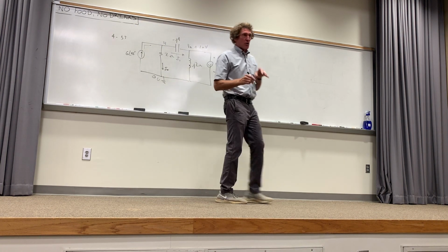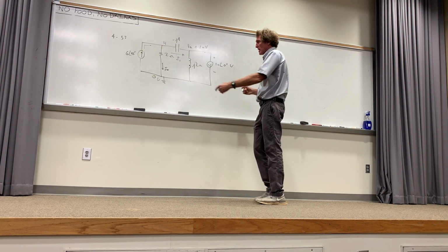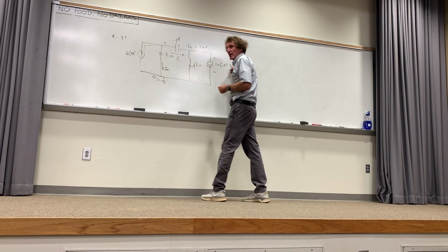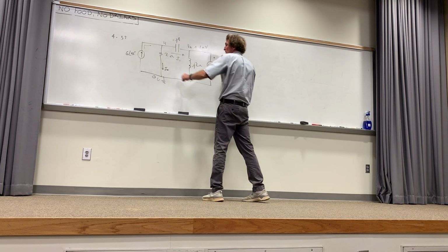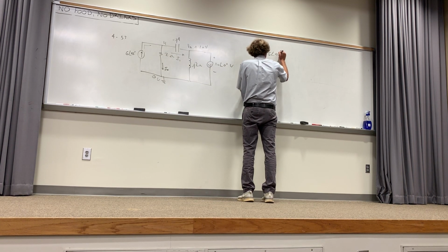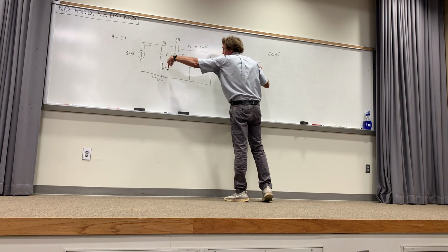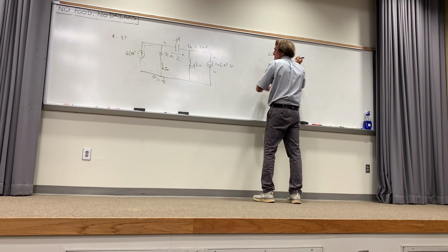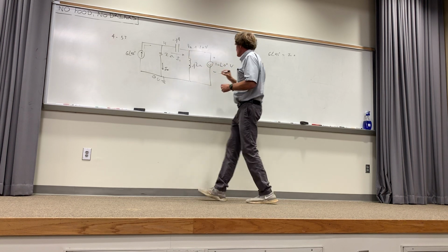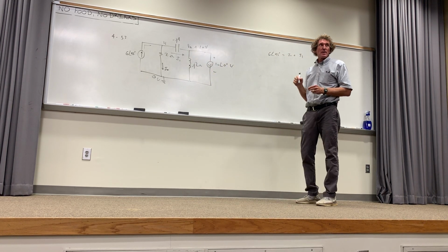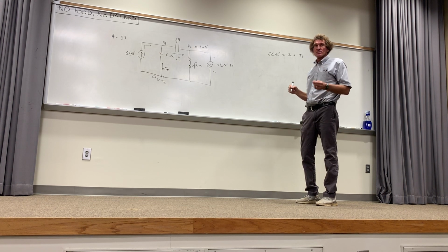So if I use Kirchhoff's current law, because that's what nodal is about, current going into this node, you all see that's a node right here, right? We've got 3 things connected. Current coming in is 6 at an angle of 45 degrees. That's equal to current going out, I0, plus I1, going this way. It's smart to write that out. I know many of you are tempted to just put it in terms of voltages. Don't do it. Write it out.